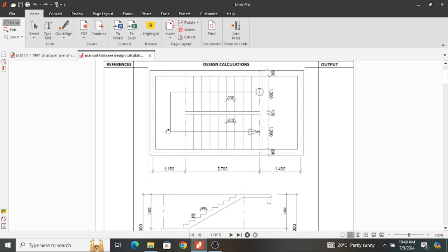So sometimes if we have steps at this section, those steps might confuse you, but use them to get the volume of concrete, then using the density, you can get the loading. Then you can distribute that loading to your supports. Just analyze your structure, look at all the supports, and consider them in your design.